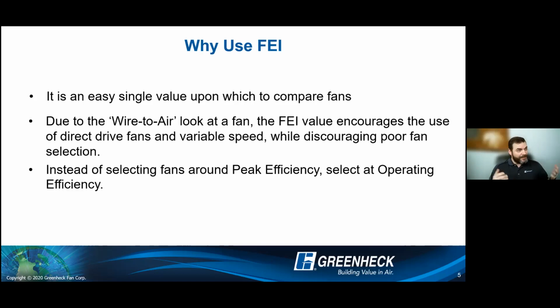Also, due to that wired nature, the FEI will encourage or push you towards certain good aspects, like direct drive fans are going to be more efficient. Variable speed, if I can actually operate at the right point versus over operation and moving more than I need. FEIs are also going to discourage just selecting a fan that is maybe not good.